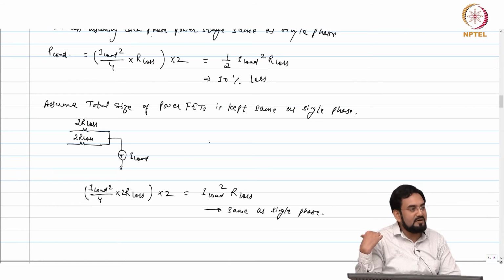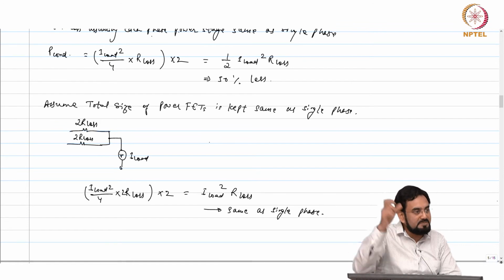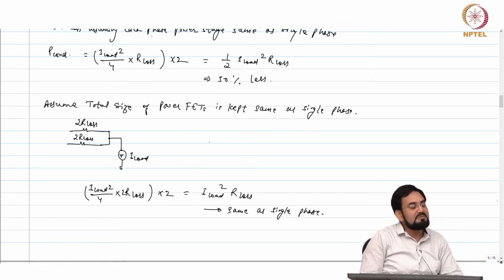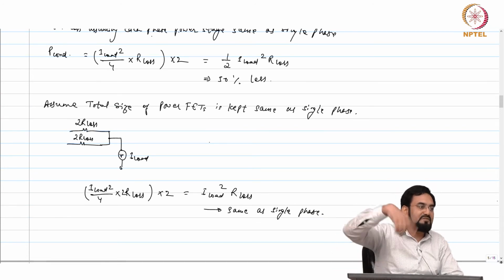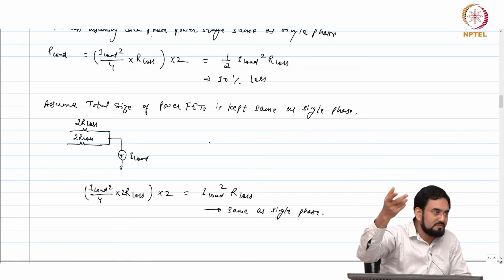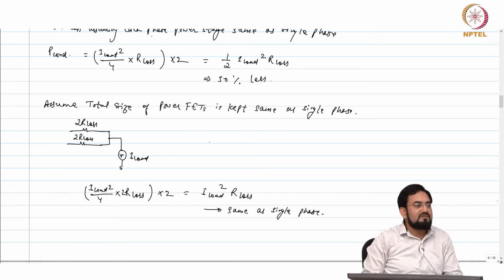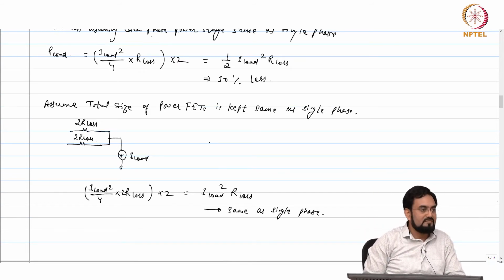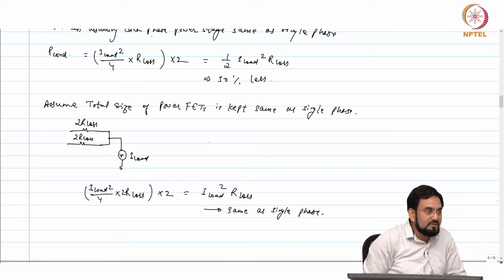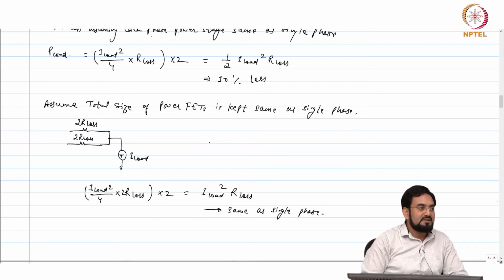So with 1 amp load current, the inductor will be seeing 2 amp current. Now split in 2, each will be seeing only 1 amp current. Correct? Because the 2 amp will be split into 2, each carrying equivalent to 500 milliamp load. So there you may see more benefit compared to buck in terms of losses, and